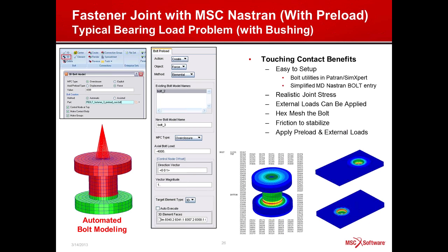So that makes it very easy to set up, and it will perform the work that you're looking at very well without having to do preload by inducing some thermal excursions. A lot of people that are trying to do this actually trip because at some point maybe you have a thermal case you have to consider, and then if you have your preload as a thermal case, you have to still compound the effective temperature on the subsequent load types. So this is not the case here. So preload is also available in linear static solutions, and you can also do preload and pre-stiffening and keep that state to do eigenvalue or modal analysis downstream in the process as well.